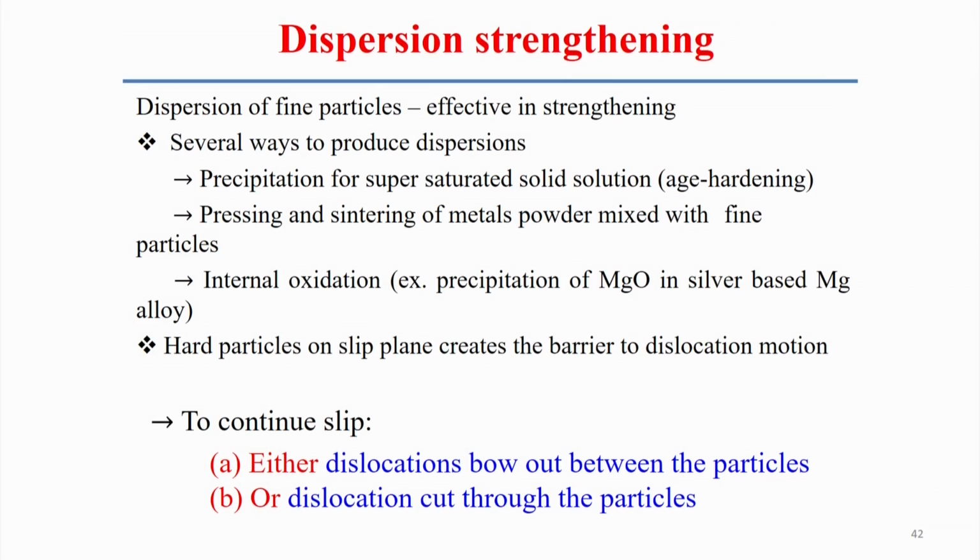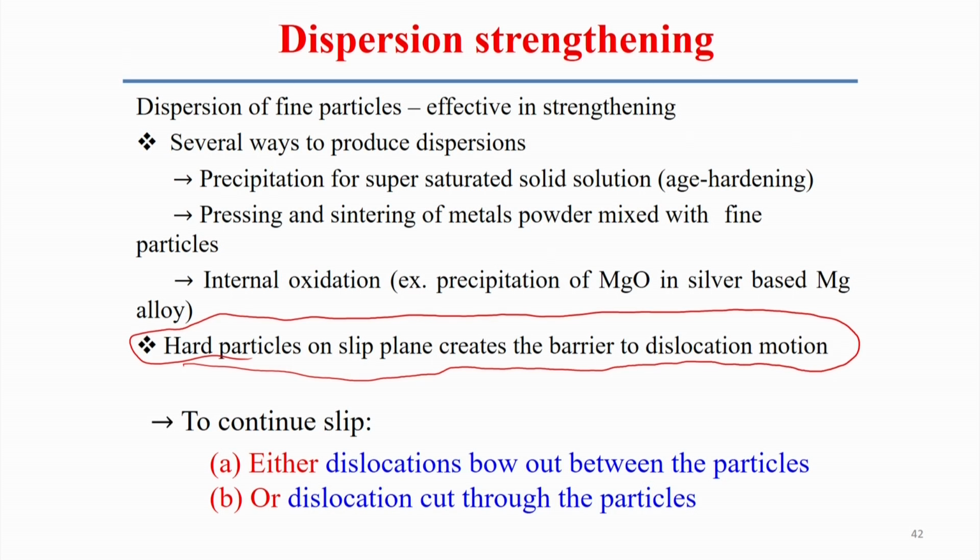But hard particles on the slip plane create a barrier to dislocation. So the presence of the hard particles creates obstacles to the motion of the dislocation. By these basic mechanisms we can impart the strength level in the presence of the dispersion particles.